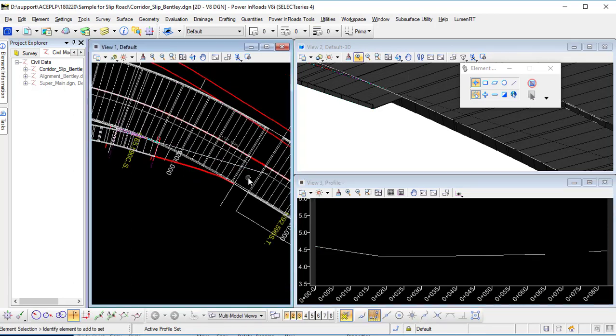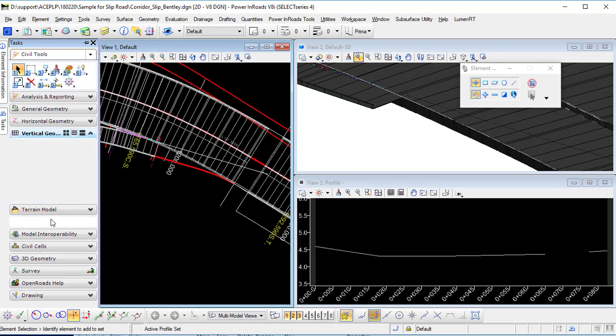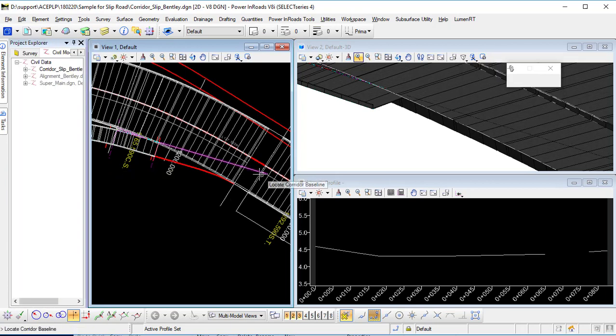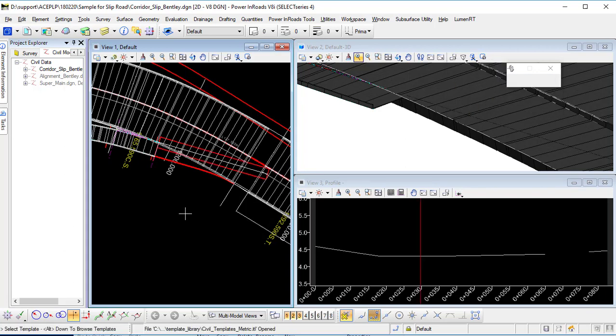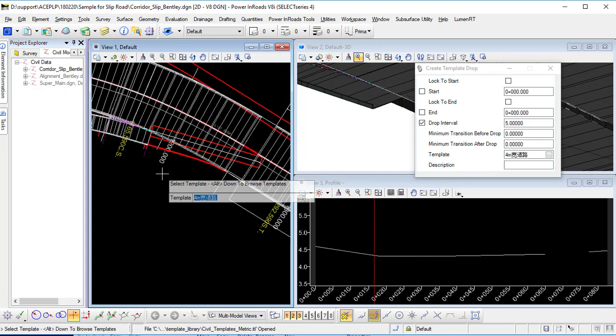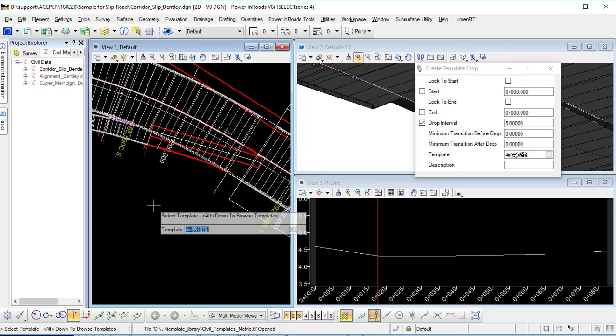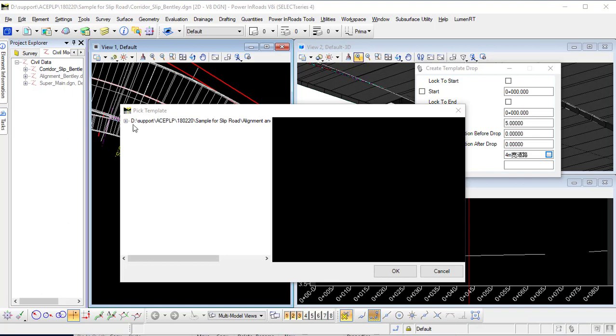Okay. So after you click active alignment, again I will go back to do the corridor modeling as I told you before. Just simply do the corridor modeling. Right click, accept it. I click snap mode. It's just for this alignment only. And then we click alternate entries to copy the template that I use.